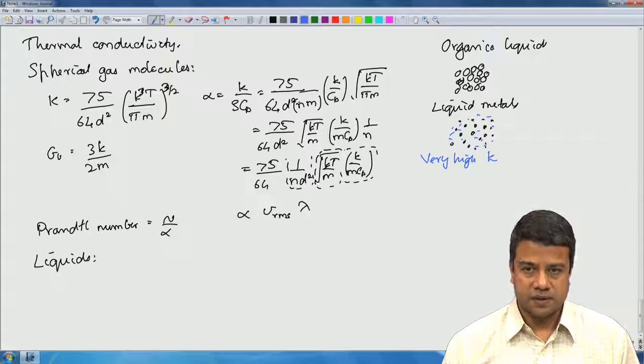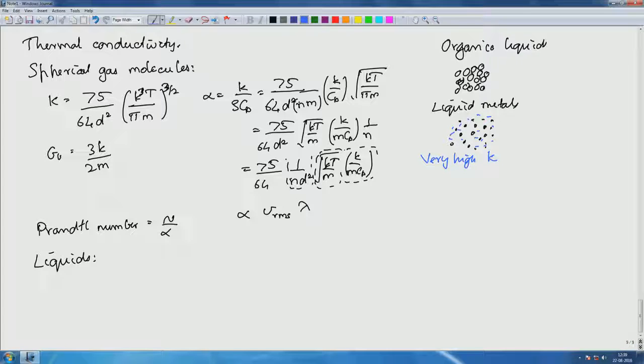So, in the previous 4 lectures, I have tried to give you a physical understanding of diffusion, how these constitutive relations arise from a molecular picture. In the case of gases, we have managed to get these coefficients fairly accurately, just based upon simple arguments. The mechanism of diffusion is due to the physical transport of molecules. Diffusion coefficient therefore is proportional to the mean free path times the RMS fluctuating velocity. All 3 diffusivities are comparable. Therefore, the Prandtl and Schmidt numbers are all of order 1.